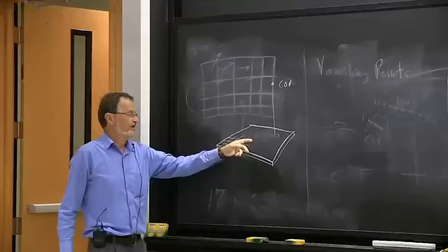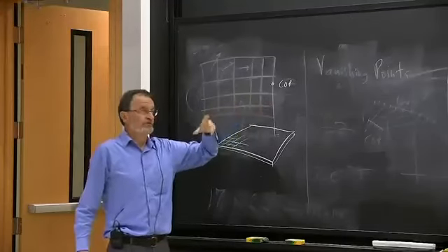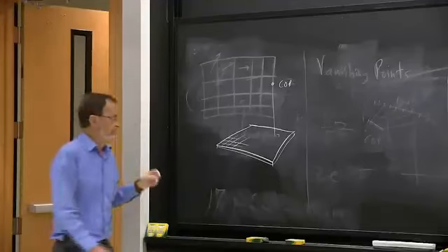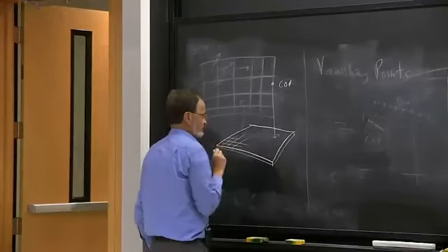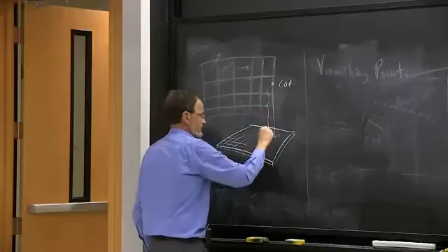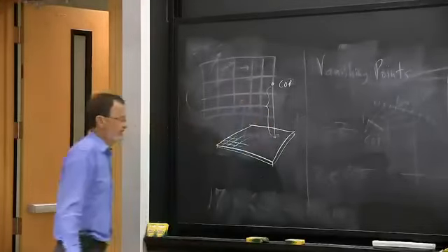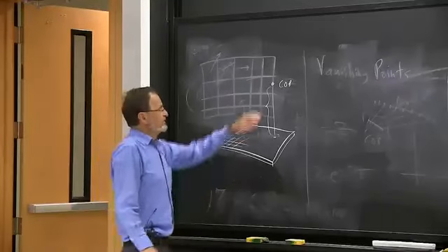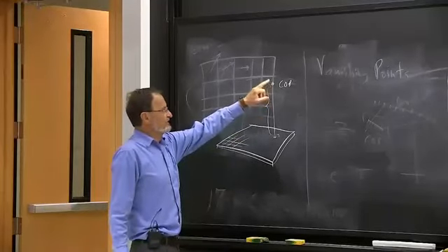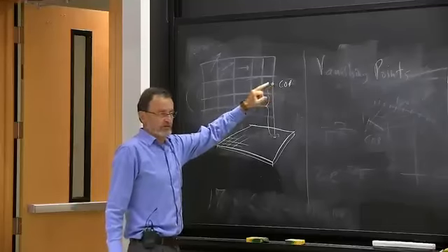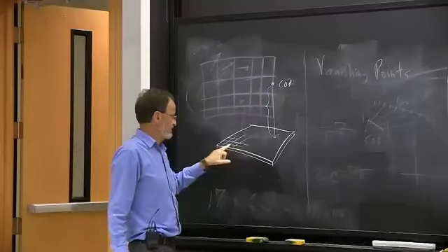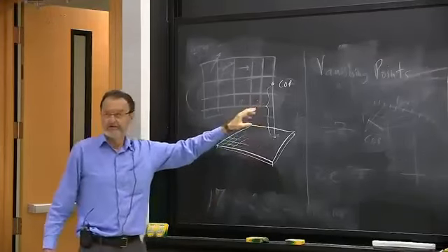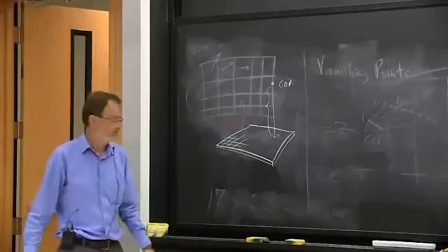So it's very unlikely that you would be able to position the lens in such a way that it was accurate to one sensor position. So we need to recover that position. And we also need to recover the height of the center of projection above the image plane. And ultimately, we'll be using a camera-centric system that's origin at the center of projection. But to do that, we need to understand how row and column in the image sensor translate into X and Y in that camera-centric coordinate system.